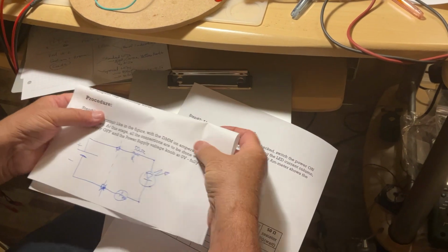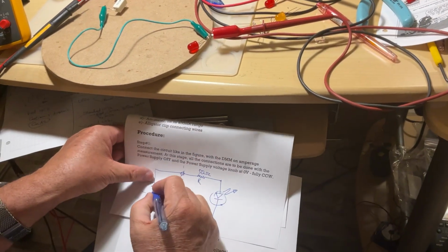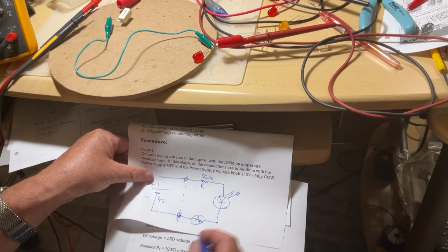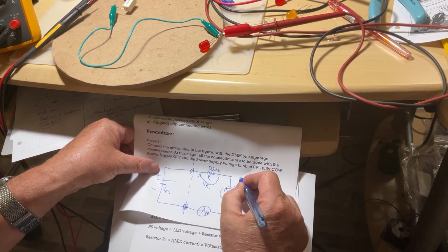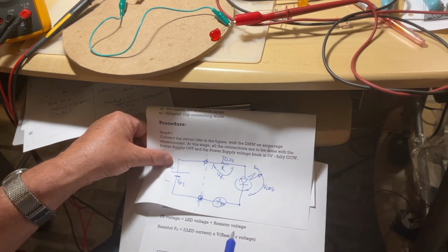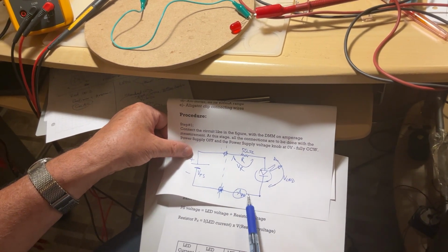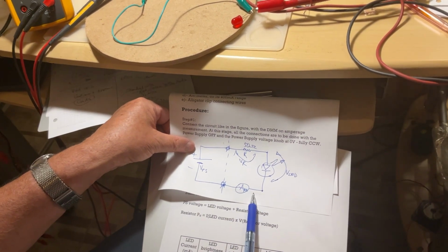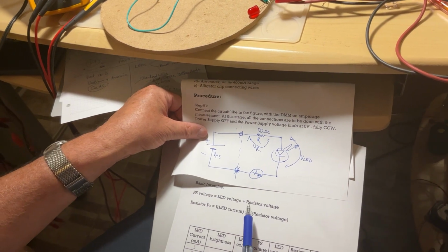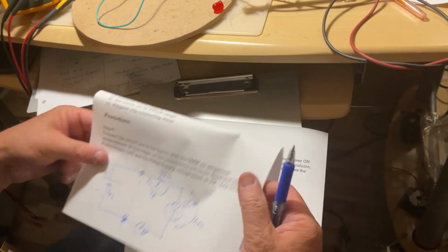The very simple relationships to use are: the power supply voltage, as you could see here in the bottom, if I give it a notation, this is the voltage of the power supply. This is the voltage I measure across the resistor. And this is the voltage I'm going to measure across the LED. Because they respect Kirchhoff's law, the power supply voltage is going to be the sum of the voltages around in series. As the ammeter is almost 0 ohms, we assume that the voltage across the ammeter is 0. So voltage of the supply is the voltage across the LED plus the voltage across the resistor. Okay? At the end, we're going to be able to calculate the dissipated power when we have the measurements. So let's start to do it.